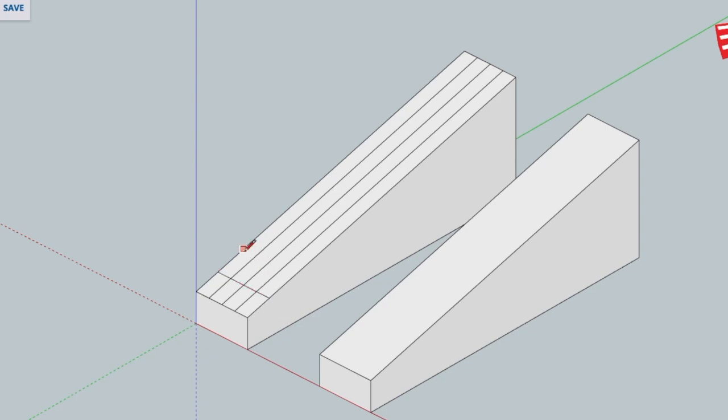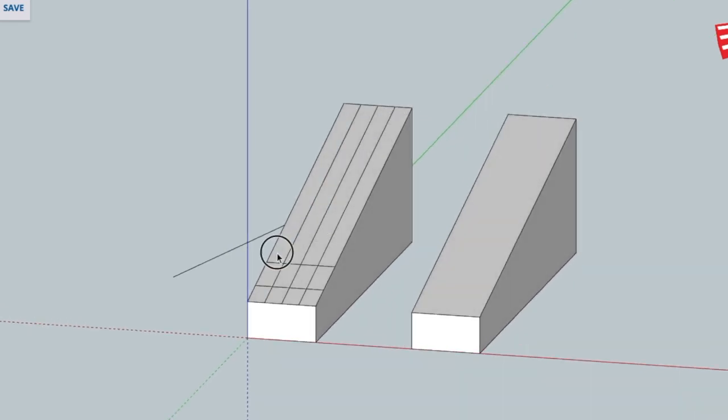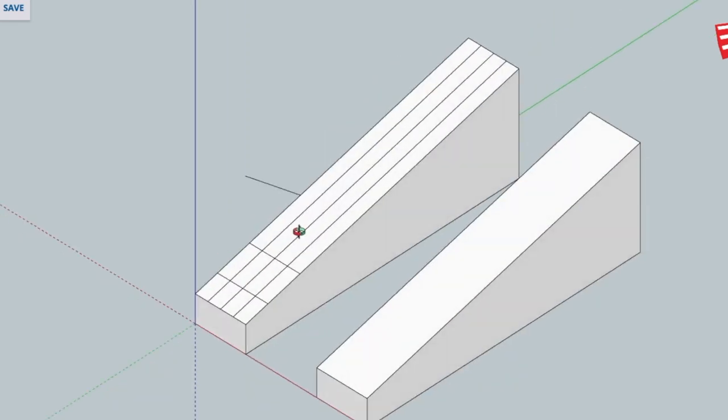and so you just try to build this the way you can. When you see me drawing stuff, you see how this is red across here, and when I crank up, it's black. But if it's red, that means it's parallel to the red axis you see on the screen, and that's usually what we want. We also want to make sure we're drawing on the face of this and not going off into the edge of something and have something sticking out of our car like that. So we want to make sure we're always drawing on the faces of stuff here.